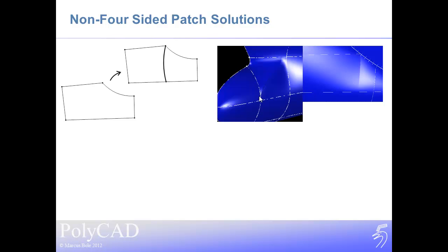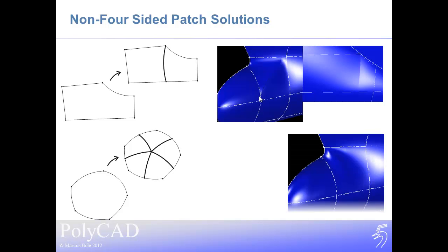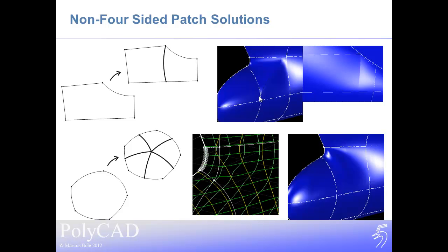This situation will probably be better solved with the regular subdivision technique. And we can see here that this surface tends to look a little bit smoother, but even so there seems to be some strange things going on. There's a shininess up in the top left hand corner which looks a bit odd. And when we start to look at our lines here, we see we've got a significant ridge running across the patch where the tangency hasn't been estimated particularly well, and potentially that central vertex might be in the wrong position.